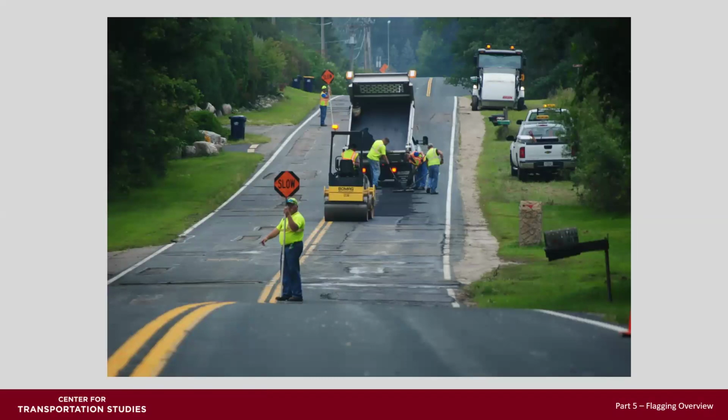What's wrong with this picture? There are cars that suddenly come over the hill and they're right near a flagger, coming in both directions. The flagger should be on the crest of that hill so they're visible. There are no channelizing devices for the taper showing drivers where to drive when you release them. And again, standing in the lane with traffic moving.